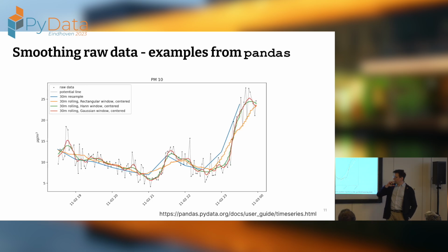So thinking about how you can do it right when you are resampling your data, I strongly encourage you to think about what's the error behind. And you see in this case here, it's the red line that uses the same 30-minute intervals to resample, but the only difference is I don't take every value that is in that 30-minute box and take an average and place one dot at a certain arbitrary point in time, but I use an asymmetrical window in this case that matches the error distribution of the underlying signal.